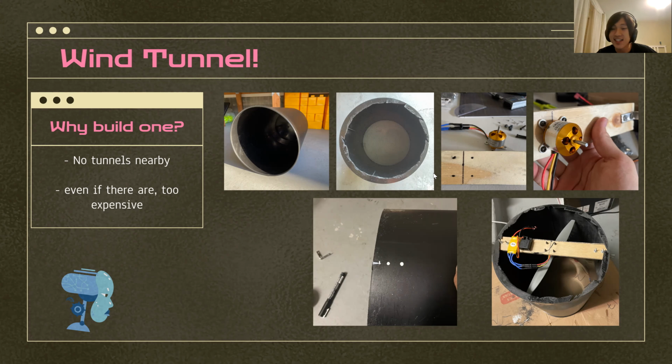So to do that, I have a wooden piece that I cut off from a bigger wooden piece, obviously. And I used a marker to draw out all the positions where I want to make holes. And I used nuts and bolts and screws to get that into place. As you can see, I get the motor onto the place. And I used 2 L-shaped brackets and 8 screws and 8 nuts to mount the wooden bar with the motor and the ESC onto the garbage can.